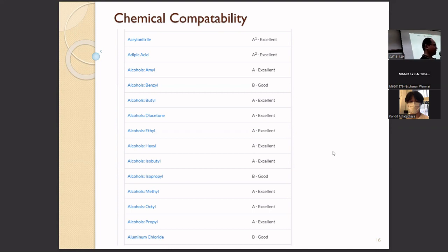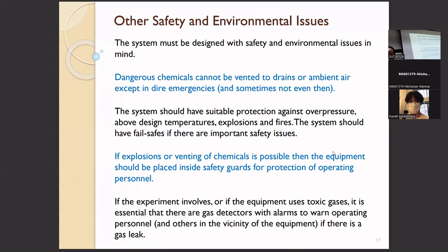You have to check if you use a thermometer. The thermometer is glass, which may be resistant to the chemical. If you use a thermocouple, it is made from metal. If you put the thermocouple in the chemical, you have to check whether the thermocouple is attacked by this chemical or not. That's right. It's a very important thing you have to check before you do the experiment.